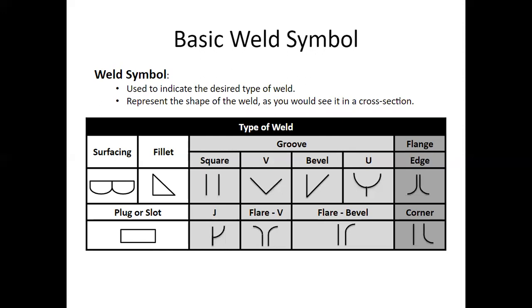So what we have here is a surfacing weld. We're going to see this right here. It's got these two little bits here. And that is going to be very similar to the padded plates you guys have done with gas metal arc welding and shielded metal arc welding. This is very good practice for running stringers, getting nice amounts of overlap, but also serves a purpose. Surfacing can be used for buildup on worn parts and materials.